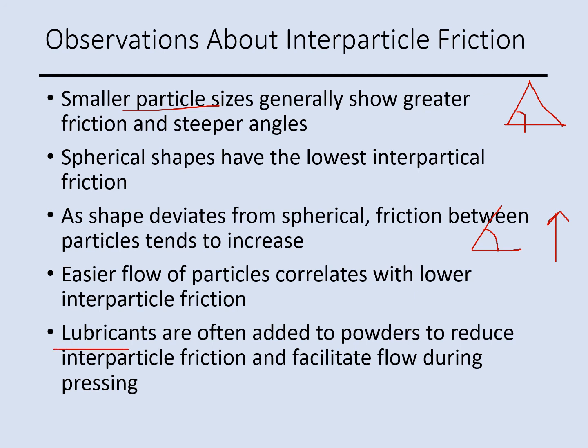Sometimes lubricant is added to the powder, which can reduce the friction between the particles, so you will have a better flow during the pressing process.